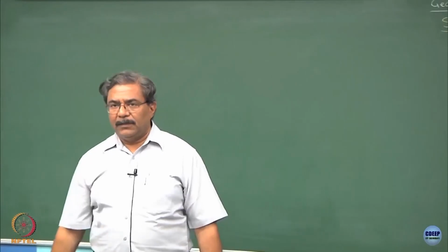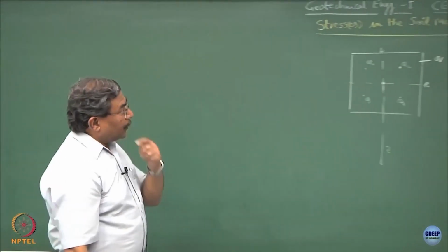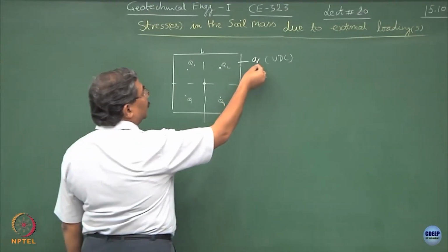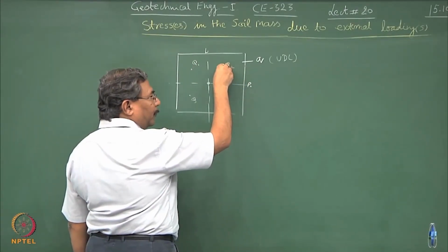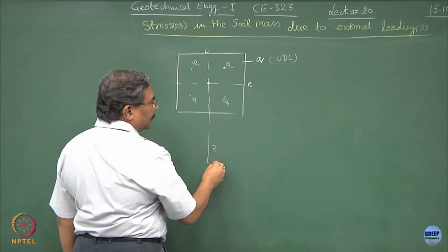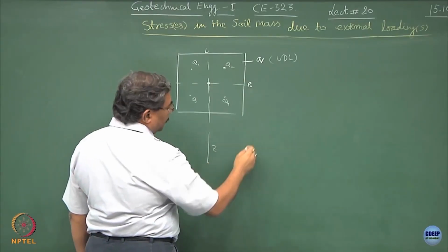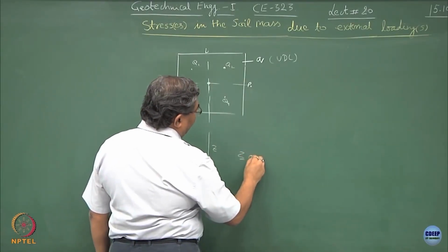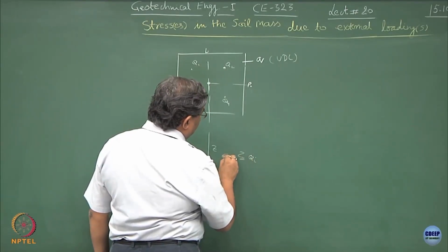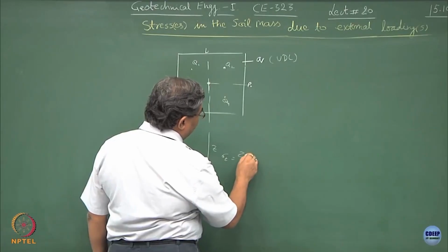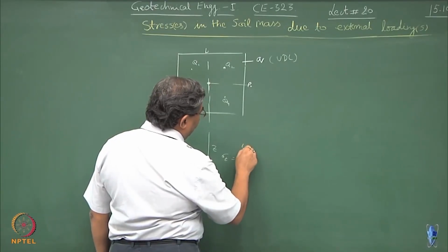I hope you can realize this. So, this is a reverse way. From Q we have converted into equivalent point loads, and for each equivalent point load I know the state of stress at a given point. I can sum this up and write the total sigma z as the summation of the sigma z's coming out of 1 to 4.